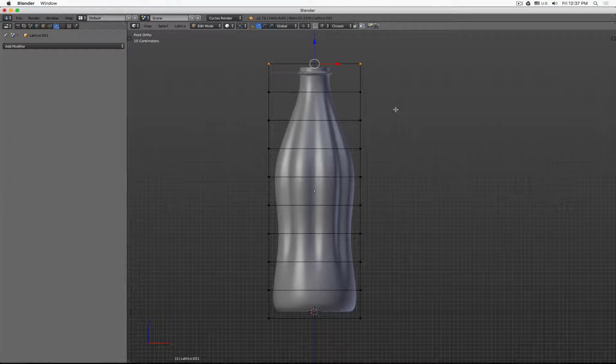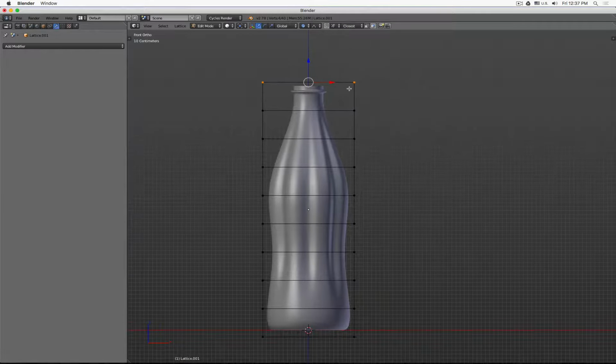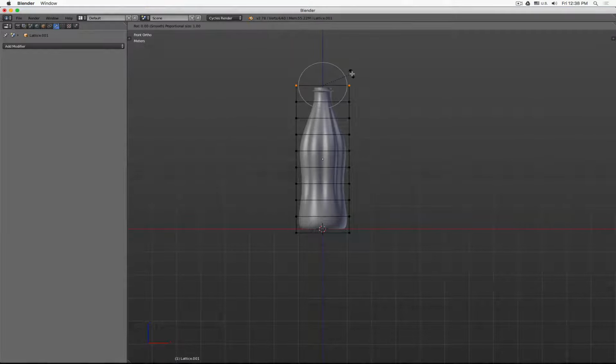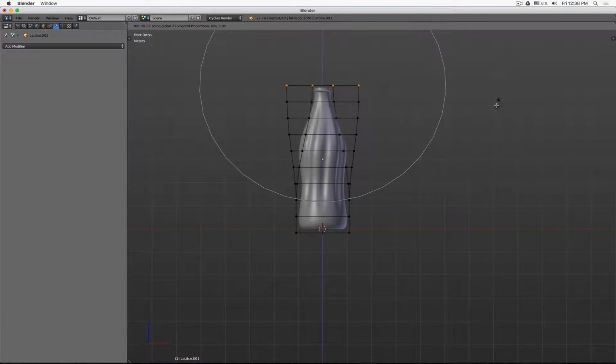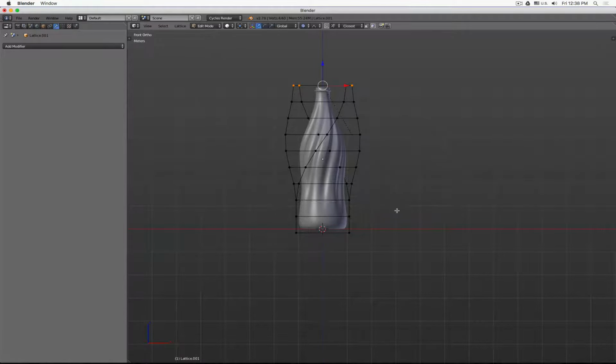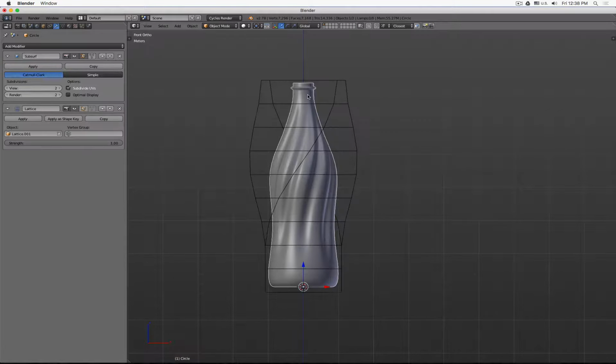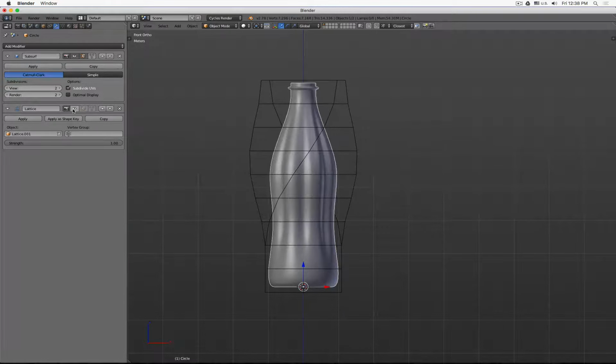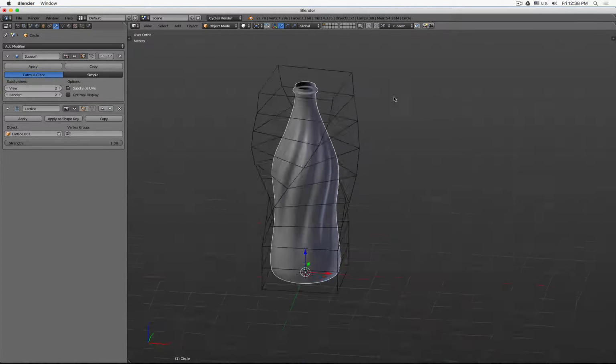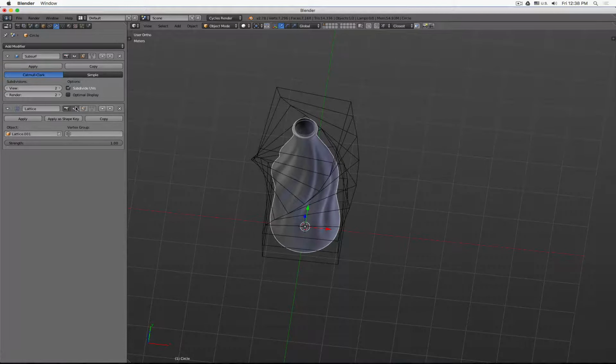This is, for example, another area where proportional editing comes in very handy. So R, Z, I have to create a bigger influence. And there you see how nicely everything spins, and then step by step it spins less until at the end it's flat. And the trick is I can always turn this on and off, and you see it changes.